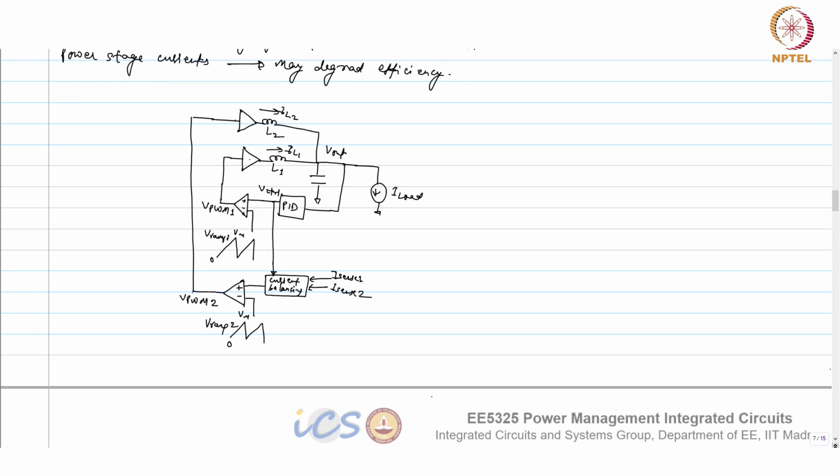So that's why, even if it reduces your efficiency a little bit due to the inductor mismatch, you don't care, because that impact is not as high as a mismatch in duty cycle. But if you have a way to determine whether this mismatch is due to RDCR or due to duty cycle, and that is also quite possible, you can measure the duty cycle at the switch node. You can always measure the duty cycle at these two, VSW1 here and here. Ultimately, you are interested in the end duty cycle.